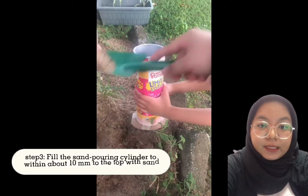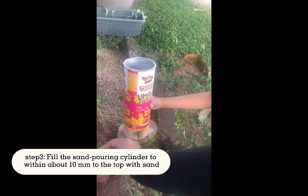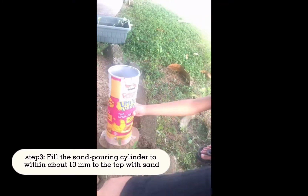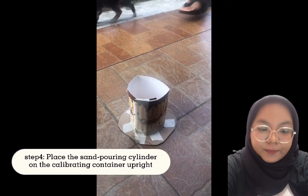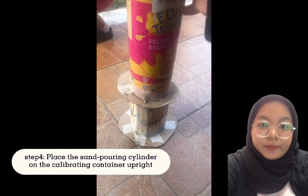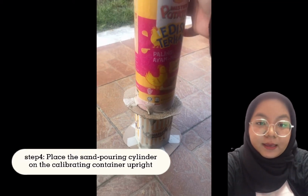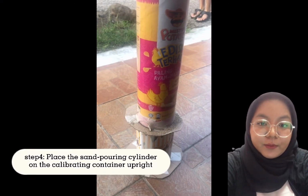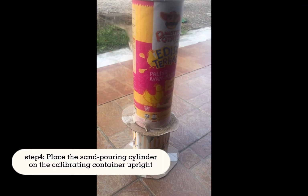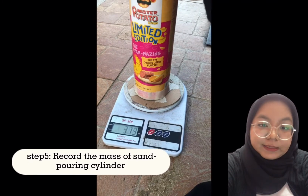Fill the sand pouring cylinder within about 10 mm of the top with sand. Next step, place the sand pouring cylinder on the calibrating container upright. Next, open the shutter and let the sand flow. Record the mass of sand pouring cylinder.